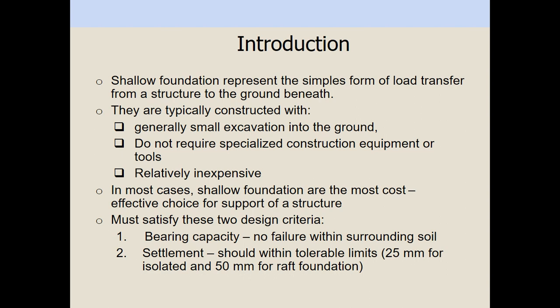Try to design using the shallow foundation first. You try using pad footing, and if the pad footing is not capable of withstanding the load, you have to change to maybe combined footing, and after that try mat footing. If mat footing also cannot withstand the load, then you have to use the deep foundation or pile foundation. That's why shallow foundation is the first attempt in your design of foundation.